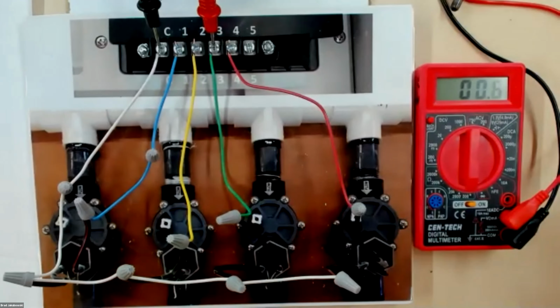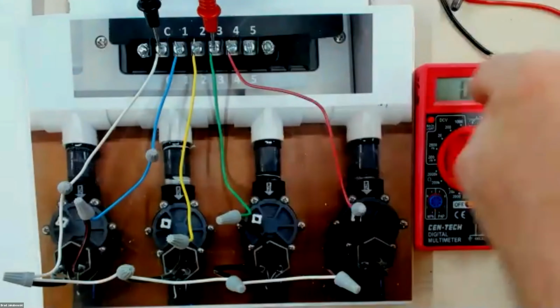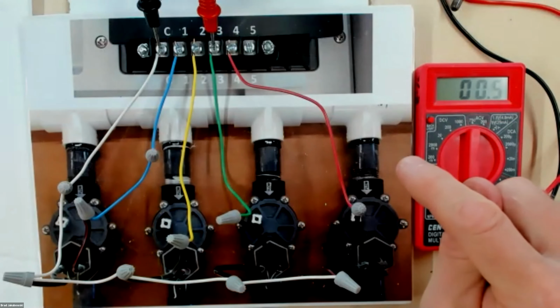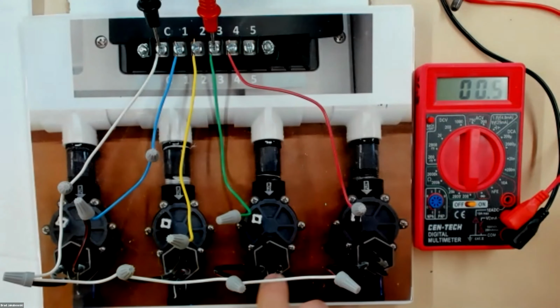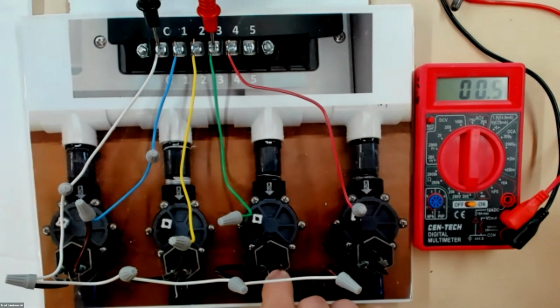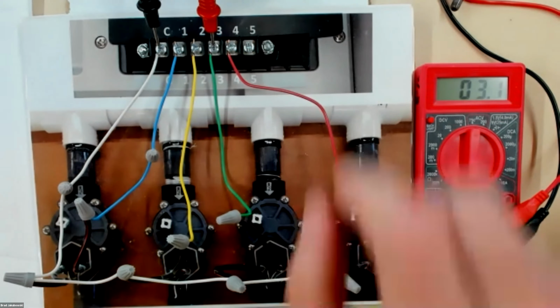So that one there should be about a 0. When you go through here and you get a different reading on this one, that's a shorted circuit. That's telling you that there's a short somewhere. Chances are you've got a bad solenoid and it's giving you a shorted reading there. Okay. Now on the next one, let's go ahead and move to number 4.